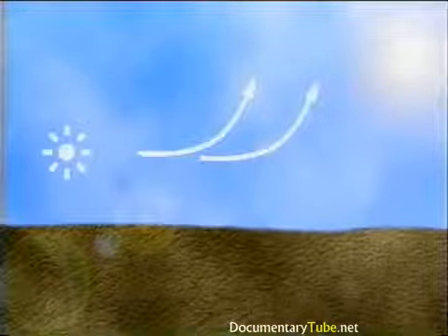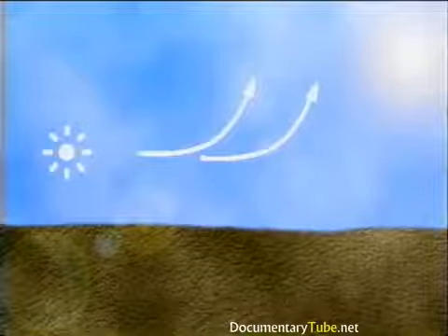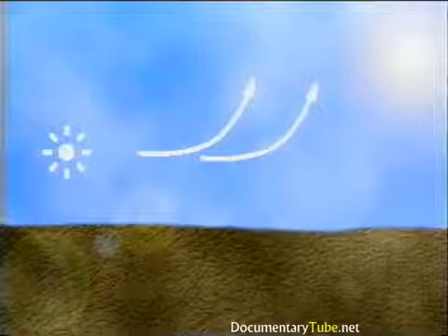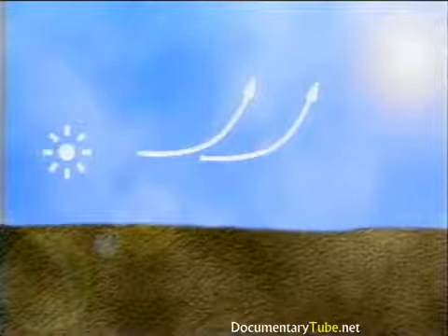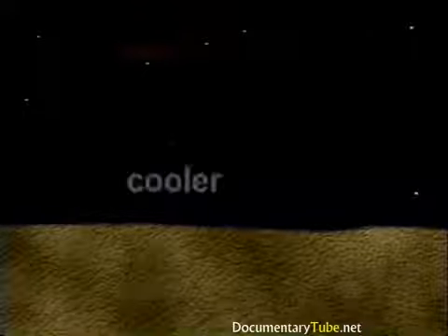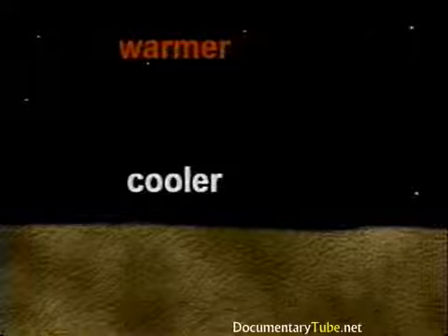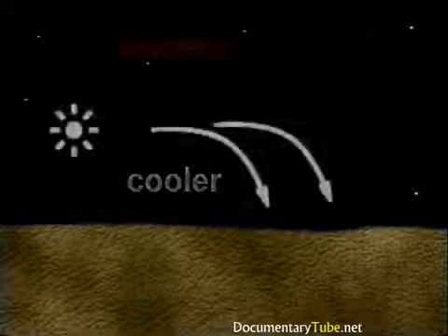The speed of sound increases with increasing temperature. This causes sound rays to bend upward away from the earth. In turn, the noise level at the receiver decreases. At night, the ground usually cools by radiation faster than the surrounding atmosphere, thus causing the air temperature to become warmer with increasing height. This is called a temperature inversion.